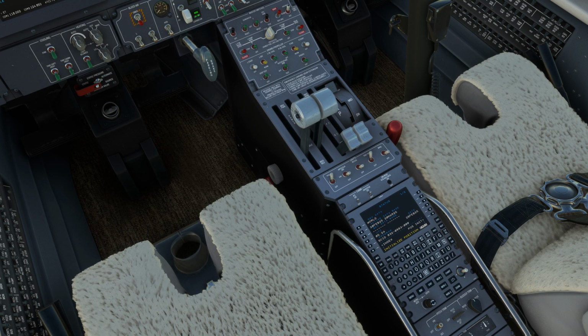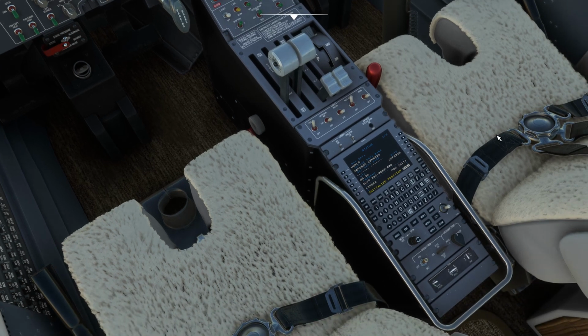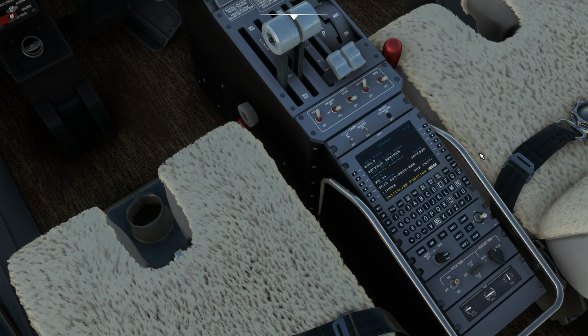So this is pretty straightforward, no philosophy here. The first page is the status, which is pretty much the first page of every flight. We should go to position initialization and click write soft 4, and the FMC automatically copies our position. And then let's execute that one.